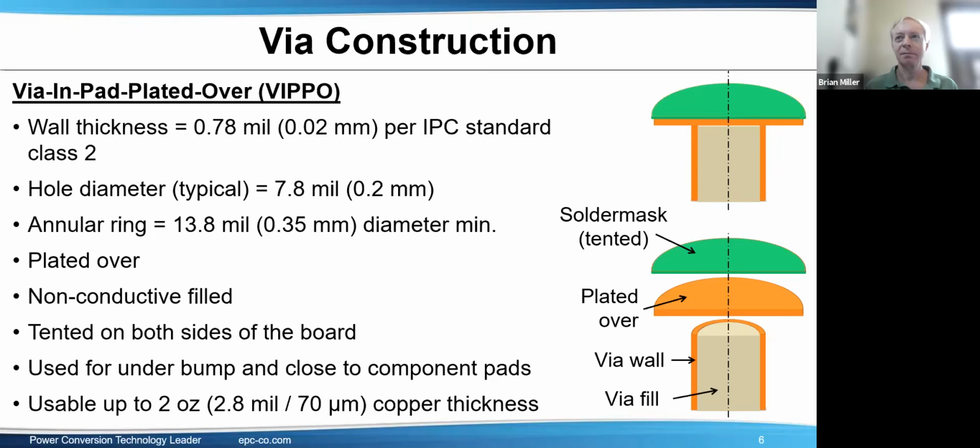Okay, this question, you might need more detail to answer, but maybe not. So we have someone who did some experiments with a GaN FET high side switch at 15 amps without a heatsink. When switched on, the GaN FET did not show any remarkable temperature rise in the beginning, but then suddenly after 10 to 20 seconds, the temperature rises to its extent and the device is burned off. What could be the reason?